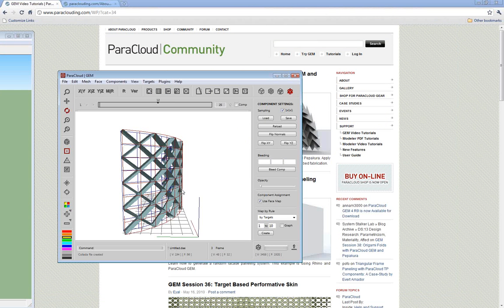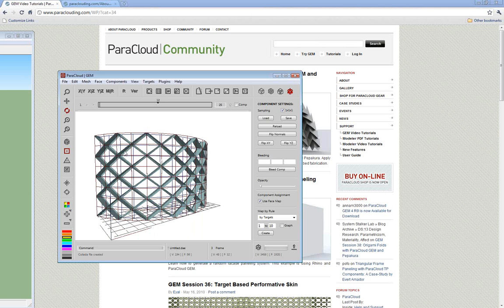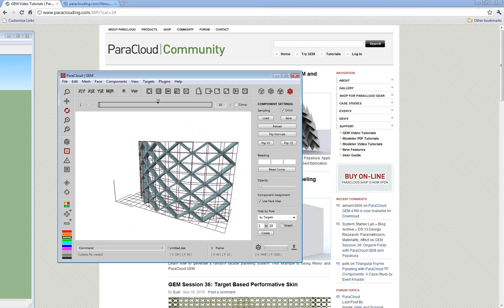is the ability to take the components into the fabrication plane, and you can assemble those together. So if you take each individual component, like what we've got here, and you don't want to print it in one go because it will take quite a lot of time to 3D print a large model like this, you can take these elements to the fabrication plane. So we could create an unfolded layout and just define spacing between the components.